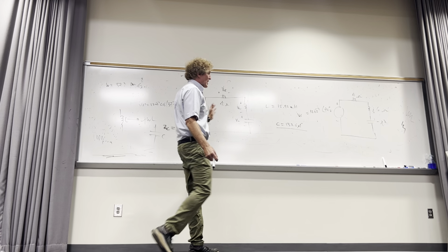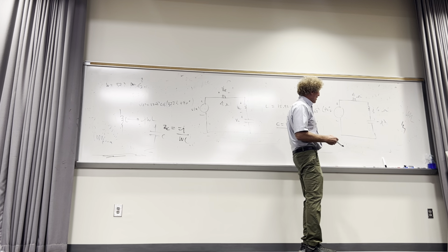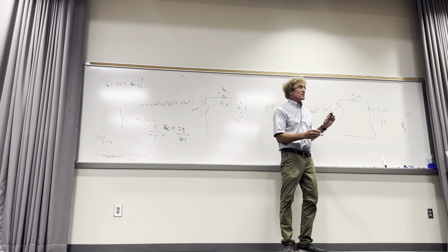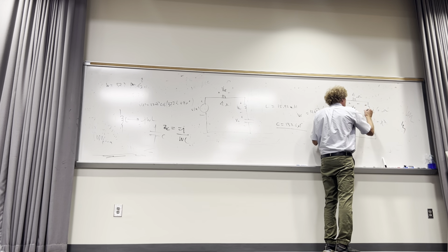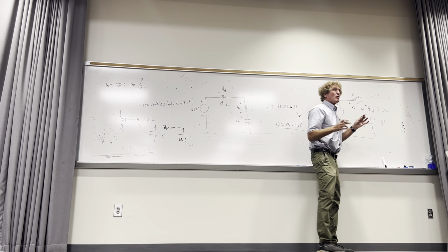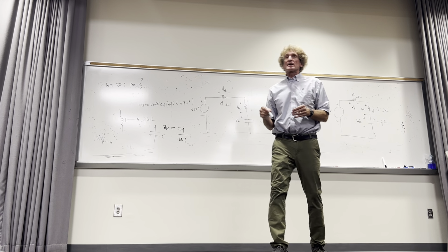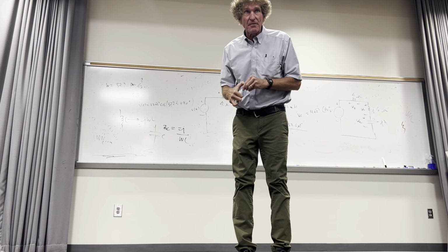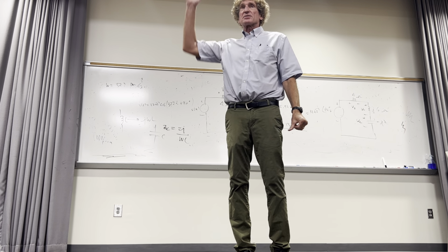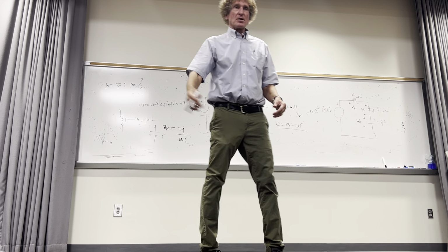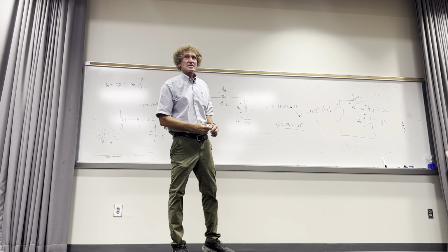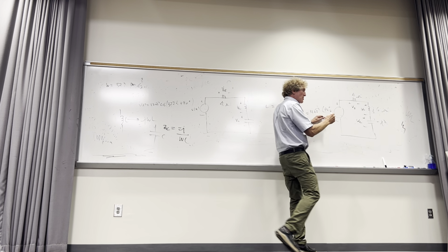Now we're in this domain called the phasor domain. You'll notice they want the voltage here, they want the voltage here, and they want the voltage here, right? The only thing you need is the current, because the current times those impedances will give you the voltage. You all with me? How many understand that? How do you get the current? Doesn't matter if they're complex resistances or not. If you want this current, we're in the phasor domain.